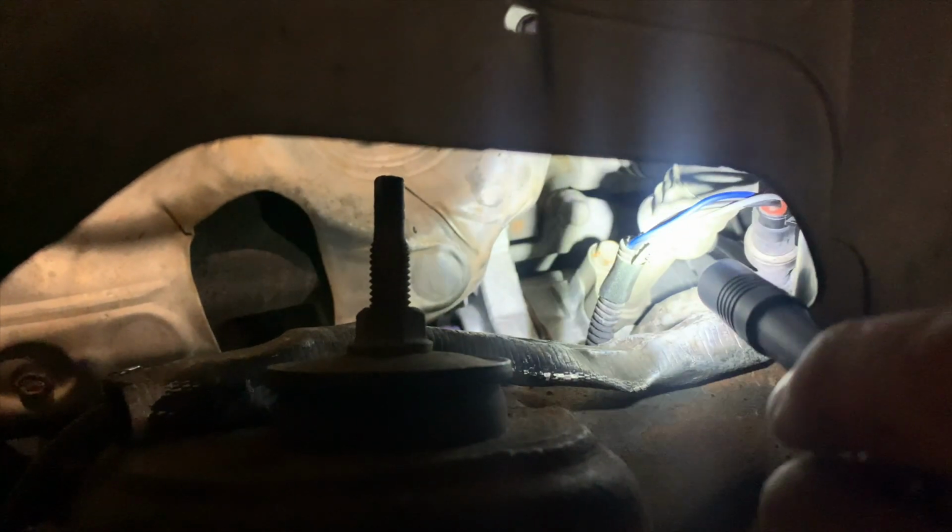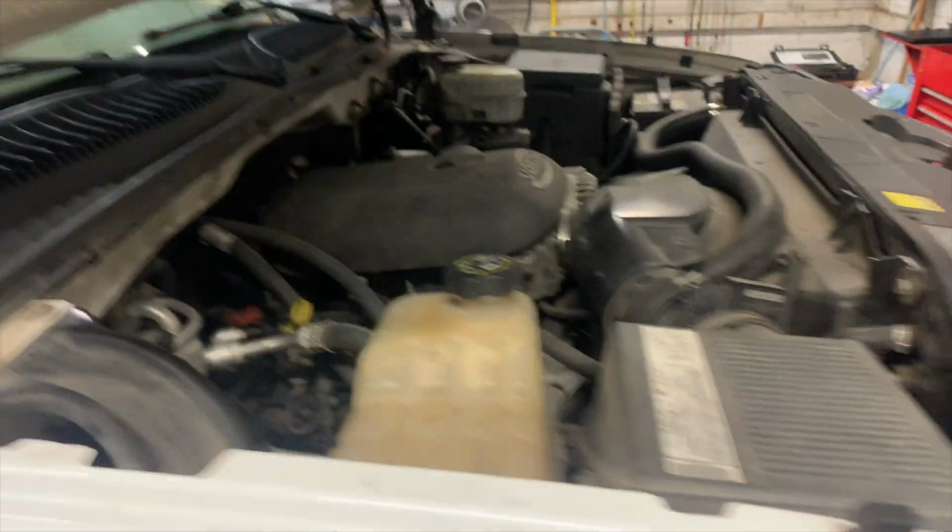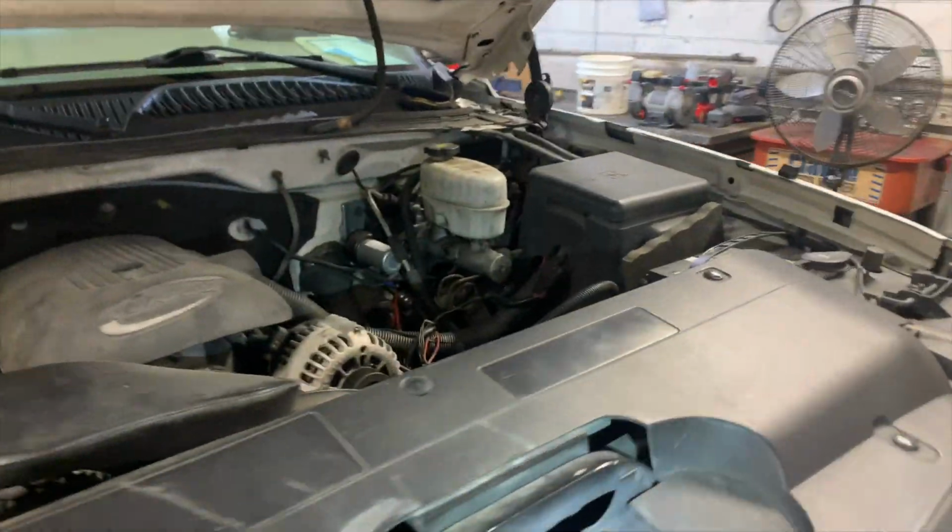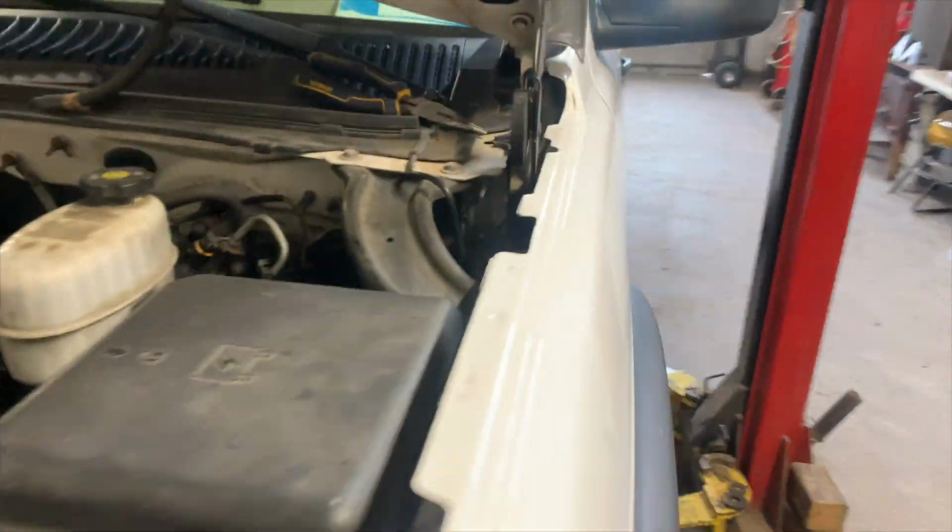Okay, I've soldered these wires back together to the high pressure switch behind that loom and plugged it back up. And the battery's been unplugged all night, so hopefully it reset the computer really good. It's crazy how a computer reset made this thing work.